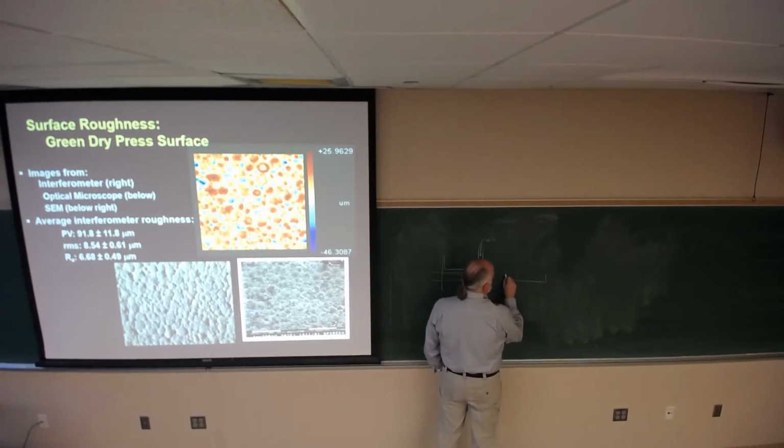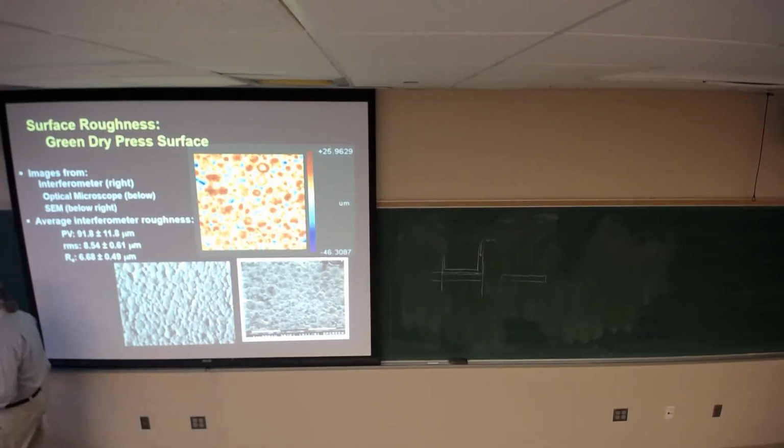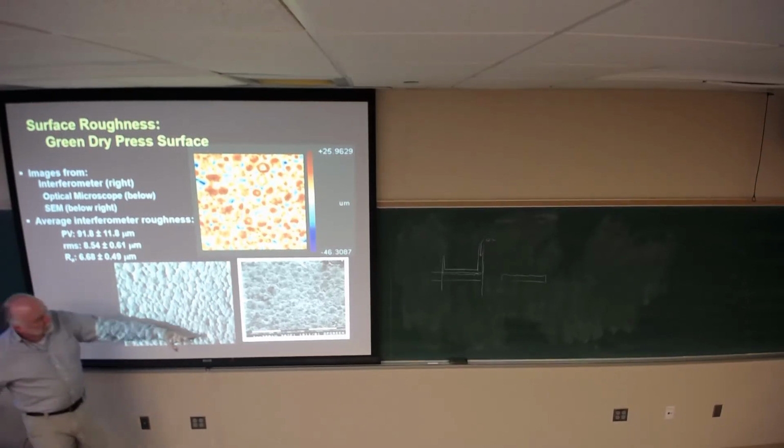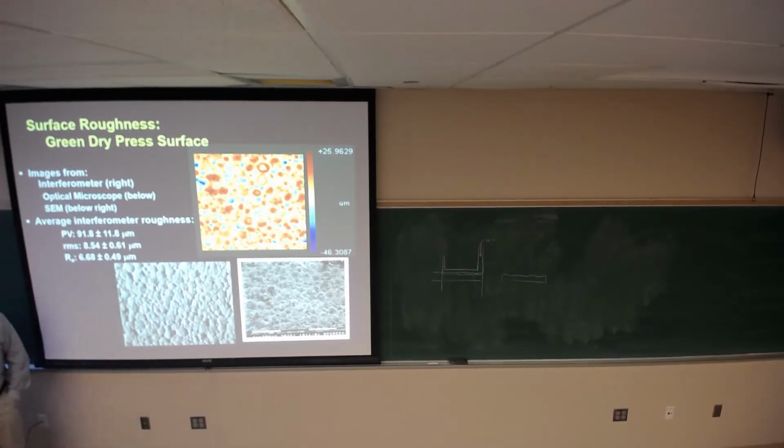But it is variable in its cross-section based on fill. That's an exaggeration. What you would get is very, very small variations that are compensated for in terms of fill by allowing greater deformation of the punch in that region. So it's a semi-isostatic die, but it's a polymer. And the polymer actually deforms around these granules rather than crushing them. And SEM images here. But this is then a surface roughness measurement. You can very clearly see the granules that were not damaged.